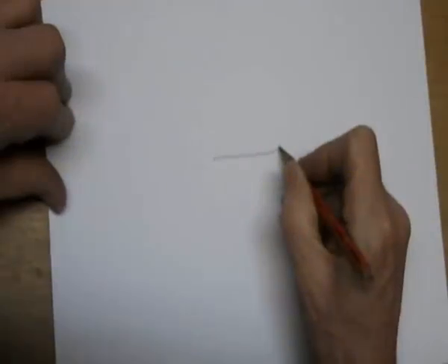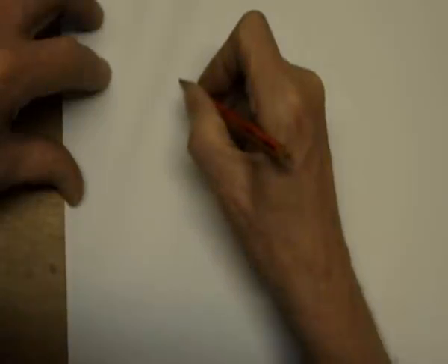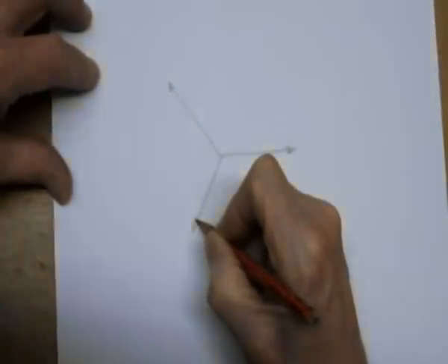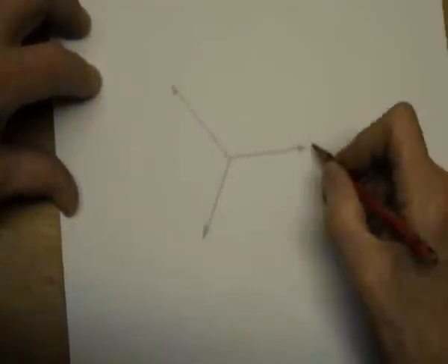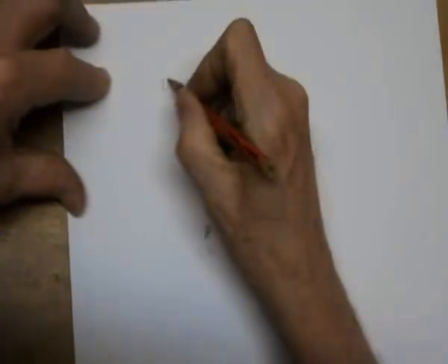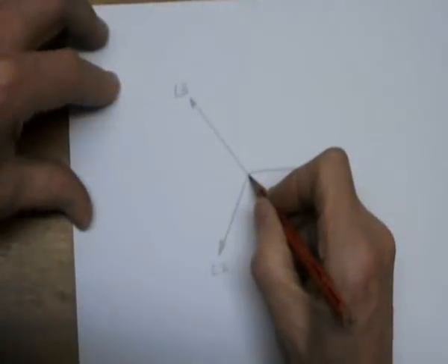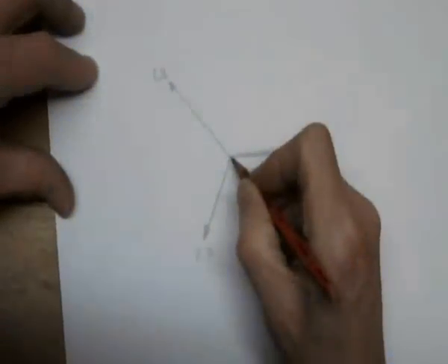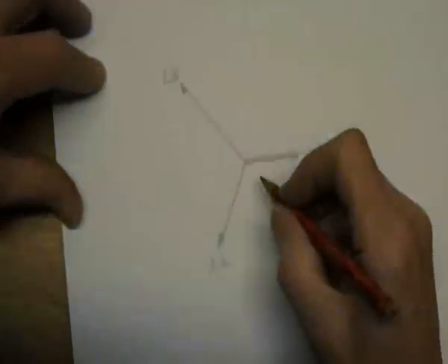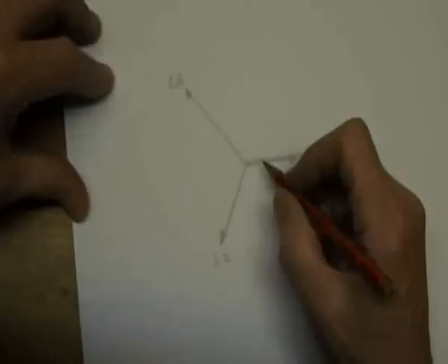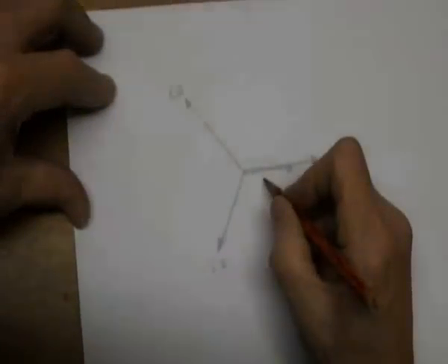It's very important that when using the analyzer, the voltage connections and the current connections correctly coincide. Looking at the voltage phasor that I've just drawn, we have L1 just there, we have L2 just there, and we have L3 just there. Let's assume that the current in L1 is exactly in phase with the voltage, and the phase angle is 0, so therefore the power factor is equal to 1. So let's call that I1.